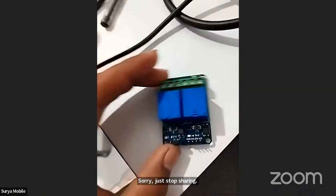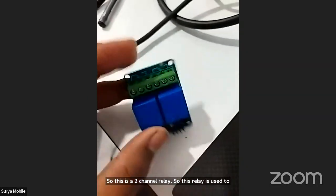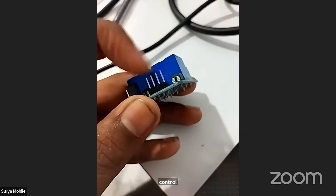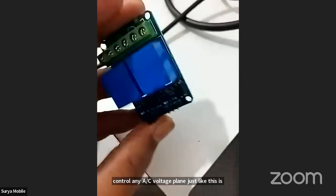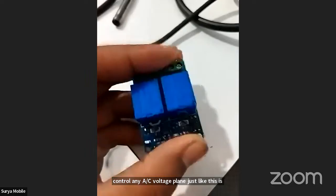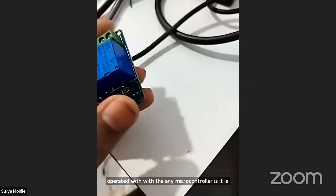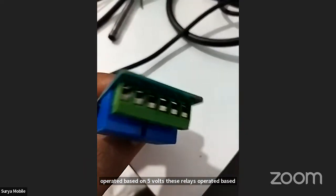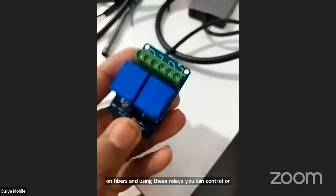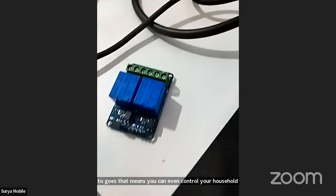So this is a 2-channel relay. This relay is used to control any AC voltage appliances. It is operated by any microcontroller, based on 5 volts, and using these relays, you can control or operate AC line voltages, which is up to 240 volts. That means you can even control your household lamps or electrical appliances.